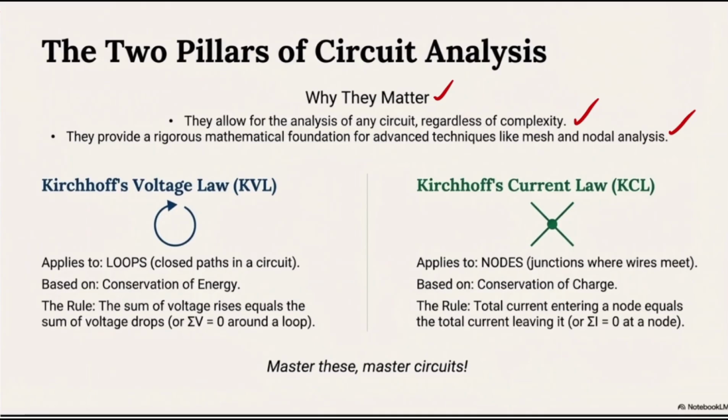So, Kirchhoff's voltage law. Let's talk about these two pillars of circuit analysis. As we just mentioned, they are important because of these reasons, and now we are going to talk about each of them in detail. The KVL, Kirchhoff's voltage law, what does it say? It says that you can apply it for each loop. The very first important thing about each electrical circuit theorem or any kind of analysis is some terminology. The very first term is loop. What is that? A loop is any closed path in a circuit.